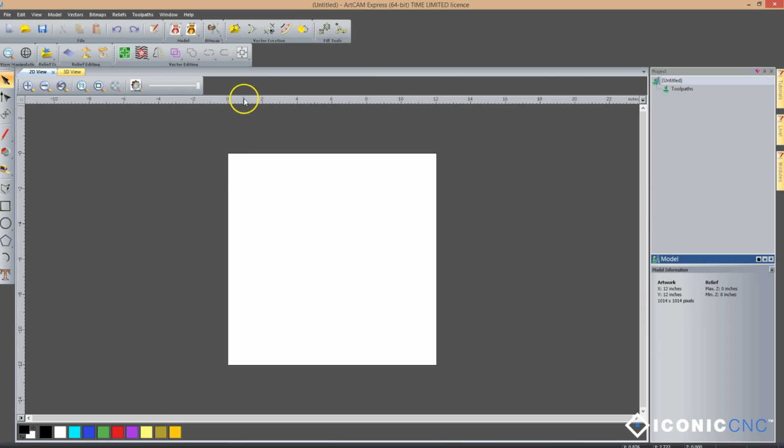Last thing I want to show you is, as you can see, some of these icons have a little arrow in the bottom left-hand corner, and that's an indication that there are other functions, several functions, at least more than one on each one of those tools. So if, for example, this one here, if I hover over it, you see it says Center in Model. If I push my left mouse button down, you'll see there are actually 8 different functions within this one tool. The first one being Center in Model. The second one is aligning my object just to the left side and to the right, to the top, to the bottom, and so on. So 8 different functions within the one tool, but each one somewhat similar to the other.